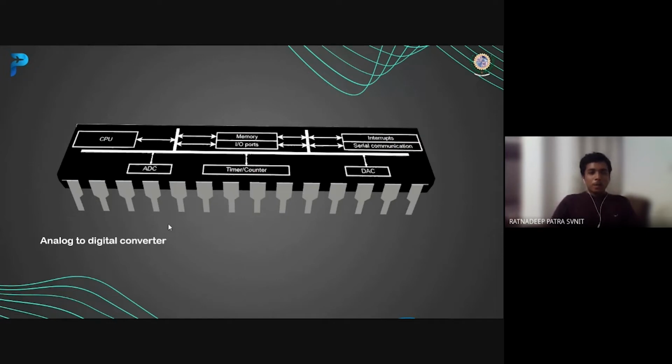For example, let's suppose we have a 10-bit ADC, and the input voltage for this ADC is taken at a max of 5 volts only. So the input range is 0 volts to 5 volts. As this is a 10-bit ADC, it outputs a 10-bit binary number, and the range of any 10-bit binary number is from 0 to 1023. So basically this ADC is mapping the input range from 0 volts to 5 volts to the output range of 0 to 1023.